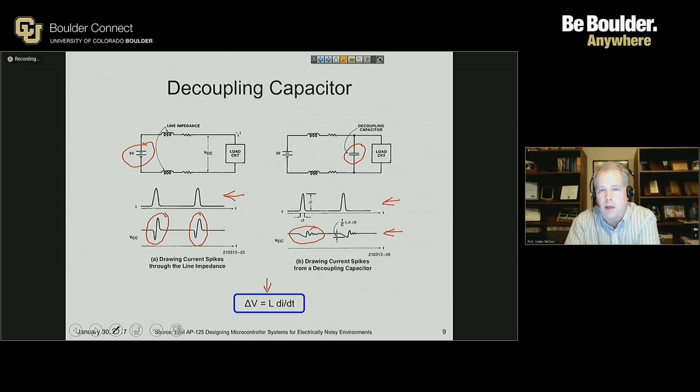There are some processors or chips which have very tight requirements on VCC. I've worked on microprocessor systems that require you to control the supply voltage to within a few millivolts. And doing that when your processor could be drawing tens or hundreds of amps of current can be a really challenging part of your design.